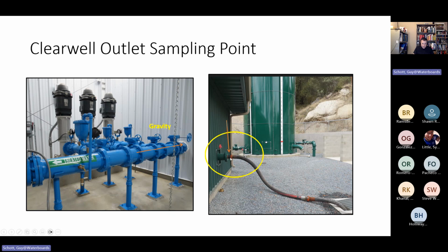And this is why I wanted to say, when talking with Clint, he thought to replace this coupler and put a sample tap on it. And as I thought about it, I don't think you're going to get any water out of it because of the flow velocity going through this pipe. It's over 7 feet per second. And I think you're going to create a vacuum pressure here where it's just going to suck in air. And so this is something we need to figure out before next week: how we're going to sample out of this line here. And I don't know if you can put some kind of back pressure on here or not, but you could try putting a sample here.